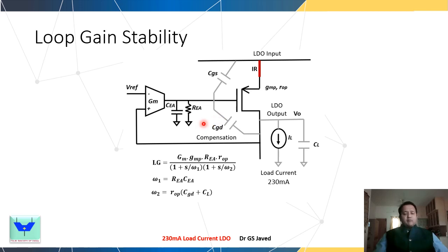Now, how does the loop gain impact? The amount of loop gain directly corresponds to the variation seen at the output load due to the amount of current drawn at this node. Also, what is the noise coming on the power line supply. These two are quantified as line regulation and load regulation. We'll look at how this contributes in the later part of this presentation.